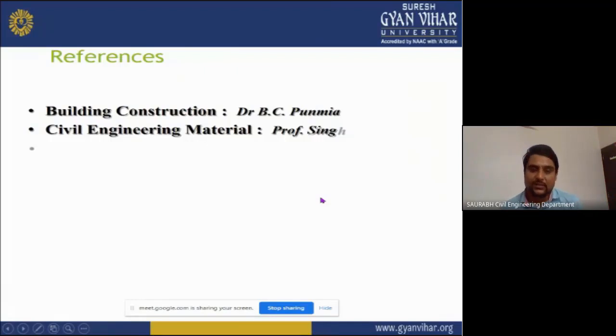This was a very important video. If you are a civil engineer, you should know the basics of brick masonry, the size, the bond, and the types of brick components, like we saw today: queen closer, king closer, and half-bat. These are the components of brick which we use during the construction of a wall or column. Thank you for watching this video.